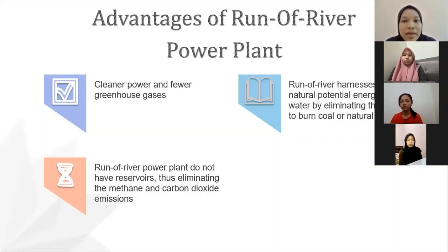For the run-of-river power plant, it provides cleaner power and fewer greenhouse gases. Run-of-river harnesses the natural potential energy of water, eliminating the need to burn coal or natural gas to generate the electricity needed by consumers and industry. Run-of-river power plants do not have a reservoir, thus eliminating the methane and carbon dioxide emissions caused by the decomposition of organic matter in the reservoir of a conventional hydroelectric dam.